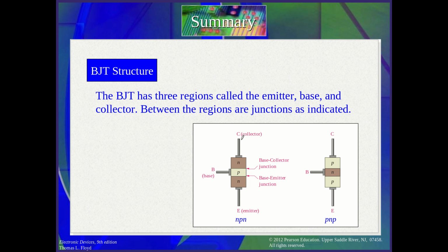Optocouplers have applications in the traffic controller, where we don't want the switching circuit to be connected directly to the circuit of the lights here. Okay, so we want some isolation. It is similar to the relay in concept. So there is no connection between the primary and secondary circuits, the controlling or switching circuit, and the power circuit, or the application, or the light in this case. Okay, this is another application, of course.